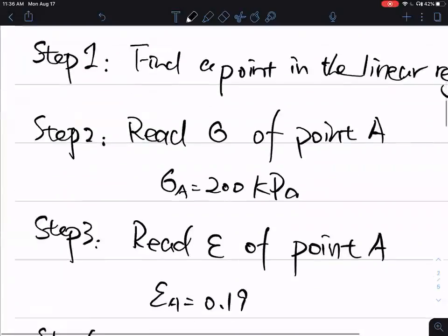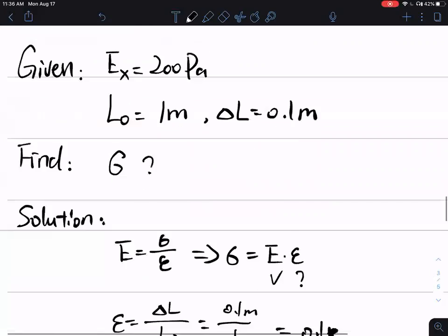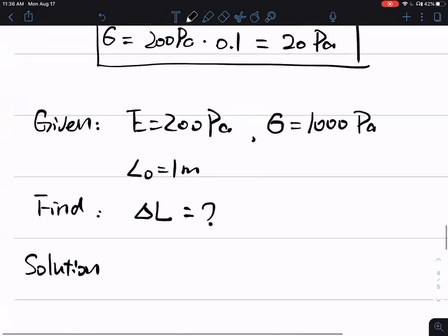I didn't tell you the stress strain diagram. I only said this sigma equals 1,000 Pascal. I never told you if that is beyond the yielding stress or below the yielding stress. So in this case, the solution to this question is unknown, not enough information. In order to solve this, either you have to ask me if that 1,000 Pascal is above or below yielding stress, or you can ask me for the stress strain diagram for this material X.